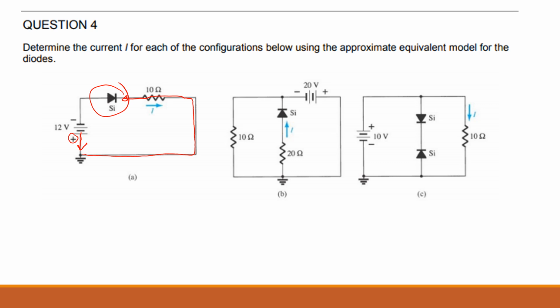No. So your diode is open. So reverse bias. Reverse bias means the diode is not letting the current go in that direction. So there is no current flowing in the circuit. Make sense? So your I is 0 because it's like an open switch. So no complete circuit there. The circuit is open at the diode, isn't it? Am I right?